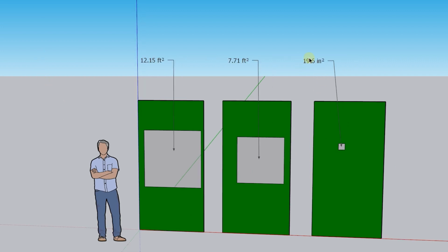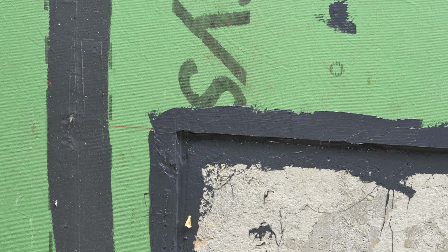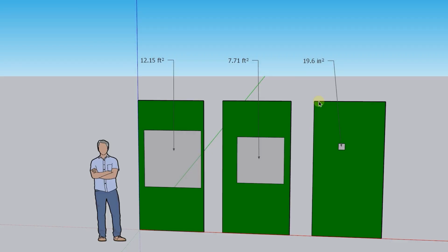And even still, this was our first round. We didn't even go through and do any of the punch out yet with the vendor. So we probably got this down to like 0.1 because we took the smoke pencil around, found a few gaps. But again, this is significant, and the difference between this and this is literally this is just the sheathing that we installed on the house, and this right here is adding the liquid flash to all the seams as a sealant to keep the water and the air out. And you can see that greatly reduced the size of the hole.